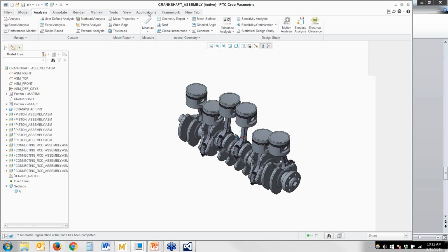Basically, what that does is it regenerates your features as necessary, or I guess in the order of your model tree. And at any point, a relation tells it to reference Mathcad for a variable. Then it goes to Mathcad to check what Mathcad says, and then pulls in that information. And so technically, you could sort of still insert it at a specific point. The only difference is it tags along with whatever feature Mathcad is coupled with in your model tree.